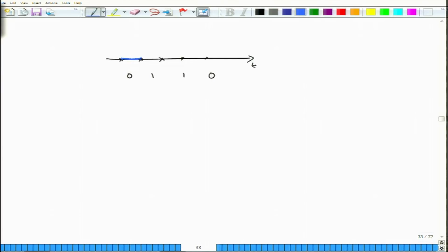Notice that the photocurrent is almost 0 when you have launched a bit 0, but when you go to bit 1, this height depends on the power P1 that you have used. If you have used a reasonably large value of P1, then this height will be large, but there will also be increased noise because a higher value of P1 means that shot noise will also increase.